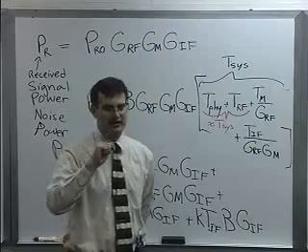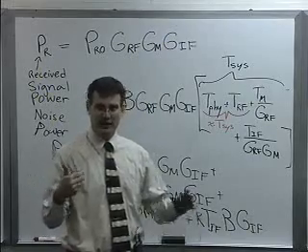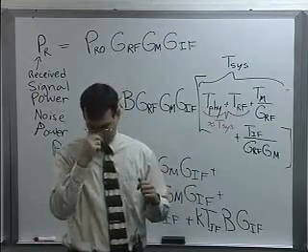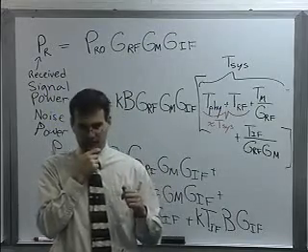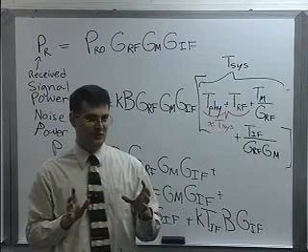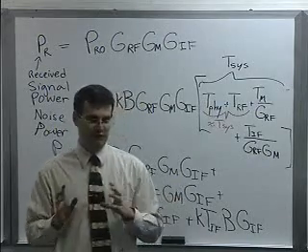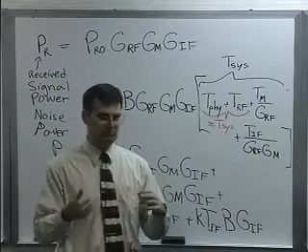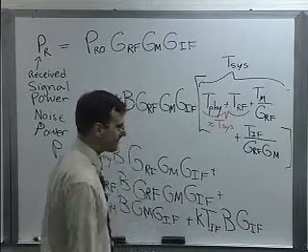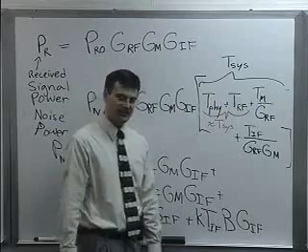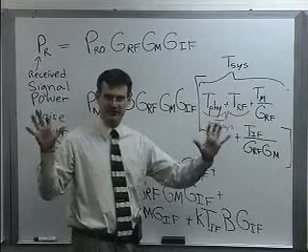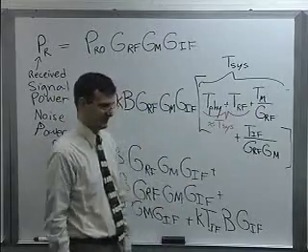Hubert. Hubert? Yeah. Hubert brought up a great point about making sure that before you do your mixing operation, you don't mix things into your signal. So that's not a bad thing to do, and it's certainly much better to do after your LNA than before your LNA. So if you need to do it there. It's going to be kind of system dependent at that point, though. It depends on what spectral real estate your signal is occupying. If it's in a noisy part of the world where you have to worry about out-of-band stuff mixing in or some other effects like these non-linearities.